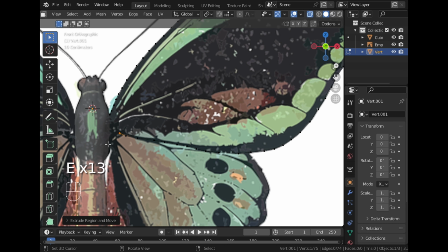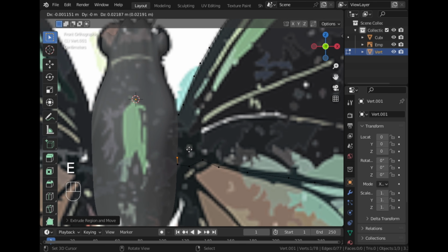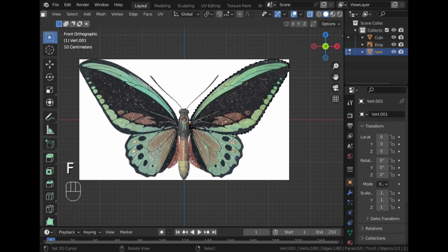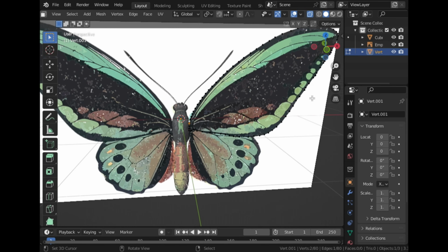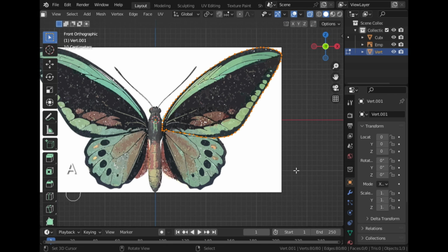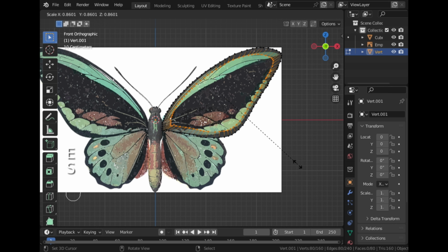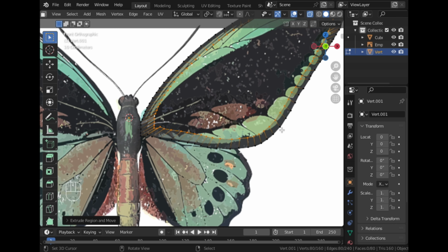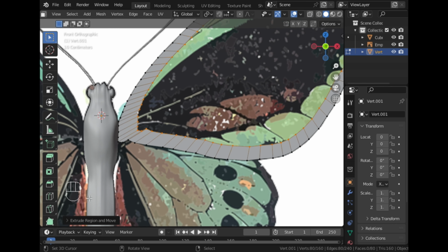When you are about to complete the extrusion process, we need to merge the initial and the final vertex. We can select both of these vertices, and here you can see, press F on the keyboard, so that the initial and the final points will be merged, and you will get a complete loop. Now you can select each of these vertices, extrude, and then scale, so that you will get a structure something similar to this.